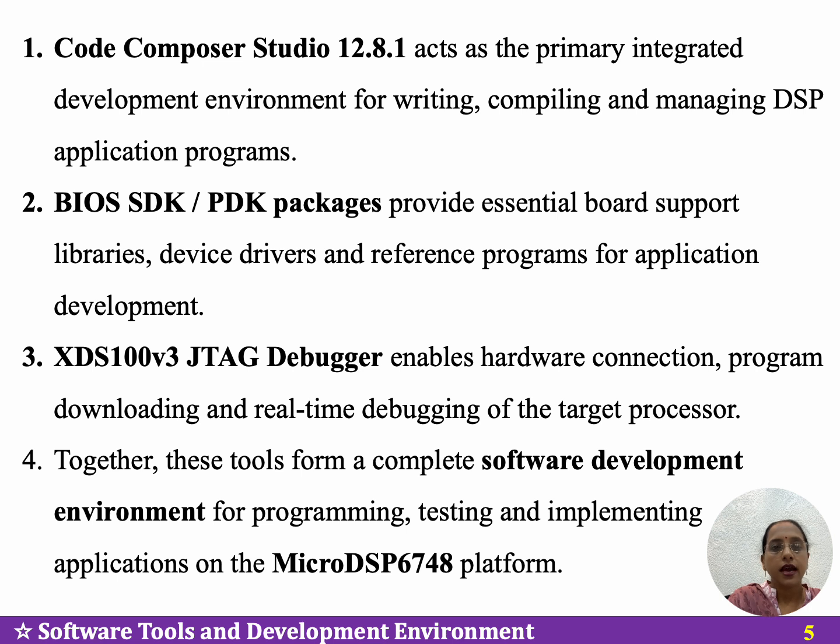Now let us understand how a new project is created in CCS. First, we open Code Composer Studio 12.8.1 and create or select a workspace where all project files will be stored. Next, we go to Project, New CCS Project, and enter a unique project name.